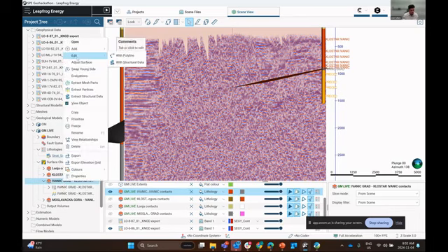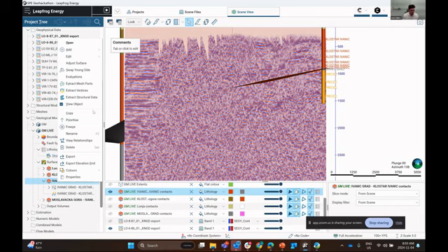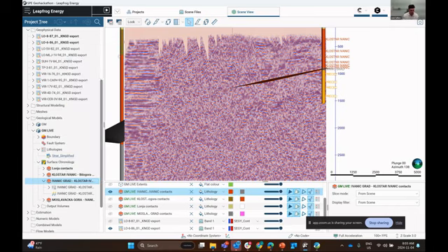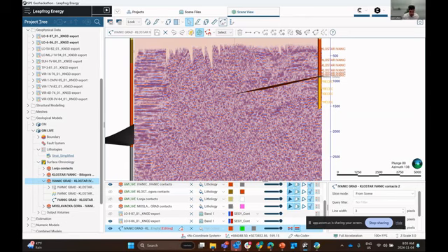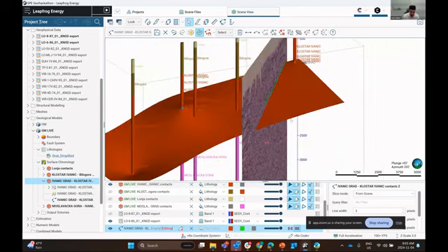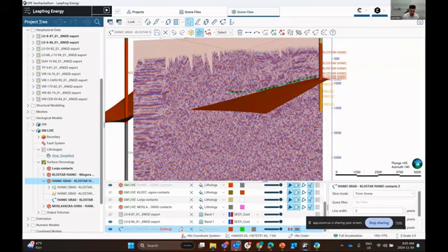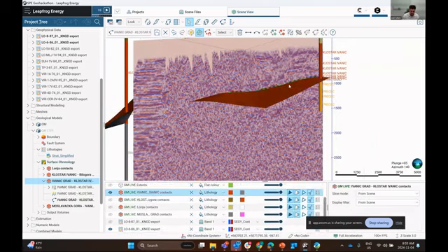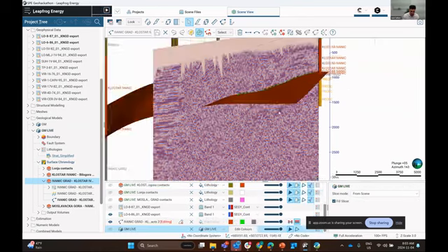So we can right-click, and this allows us to essentially draw our own interpretations in 3 dimensions, which is going to adjust the structure of not only the surface, but then the associated volume. So we can right-click, edit with polyline, and we can adjust the structure of this surface with a polyline that we draw directly in 3 dimensions, using a polyline that conforms to the structure of this 3D surface. We'll press save, and then that surface will then update based on the structure of this polyline.